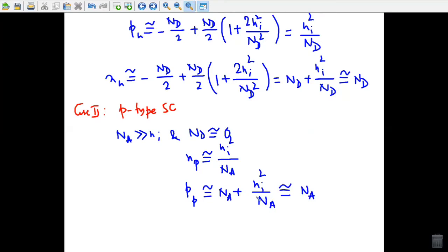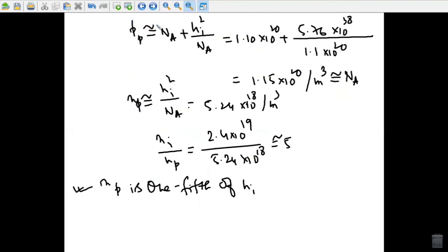So the density of majority carriers is thus approximately equal to the density of impurity atoms at usual ambient temperatures. On the other hand, because of the recombination process, the density of minority charge carriers remains significantly below the intrinsic Ni or Pi level. The following example can be helpful in understanding in more detail.